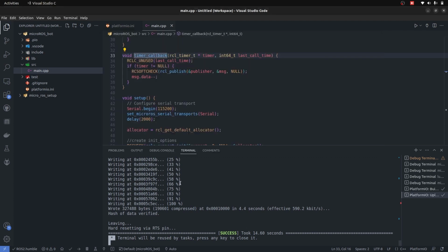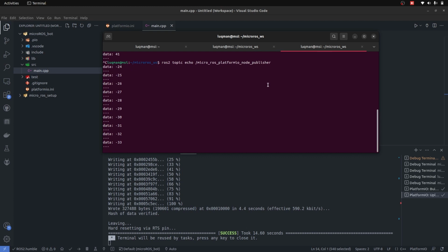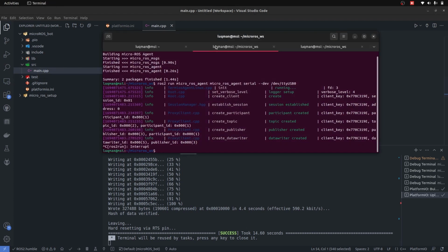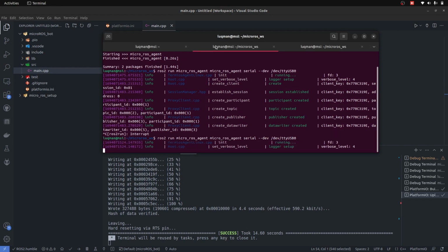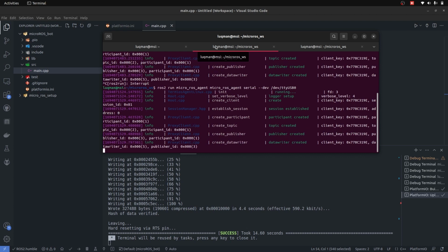This time it is going to be giving us a negative value. We will go through the main code that is written here because we have to be driving the robot, but just understand the basic process here, which is simply uploading the code from the main, then running the agent directly and restarting your ESP32. These are the 3 steps that you have to be doing whenever you want to make the ESP32 communicate with the ROS2 system on your laptop.